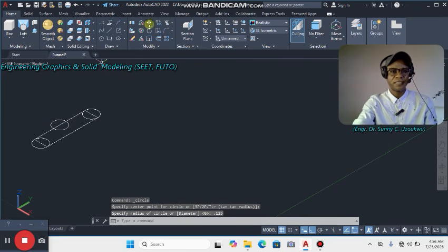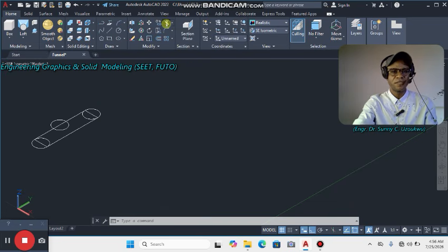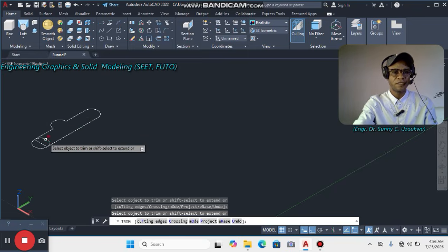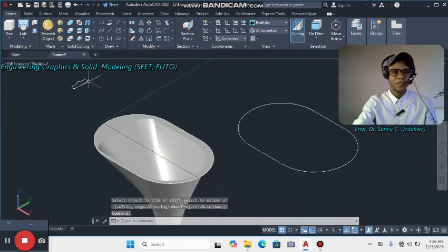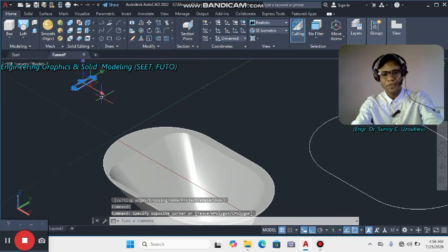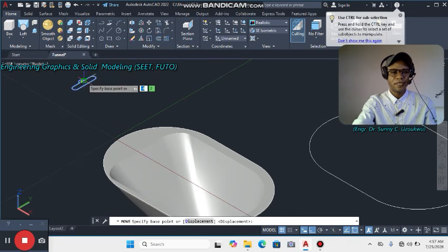So after inserting these curves, what do you do? I actually don't want to put circuit, but I just want to achieve something at the end of the day. Take a trim, get it off. Alright, you see, this is actually what I have in mind, and this, and this, and this. Very good. So next to that is to pick this up. Okay, I can make it a single entity. I've told us how to do that. Select, say enter, J enter, and that makes it a single entity.